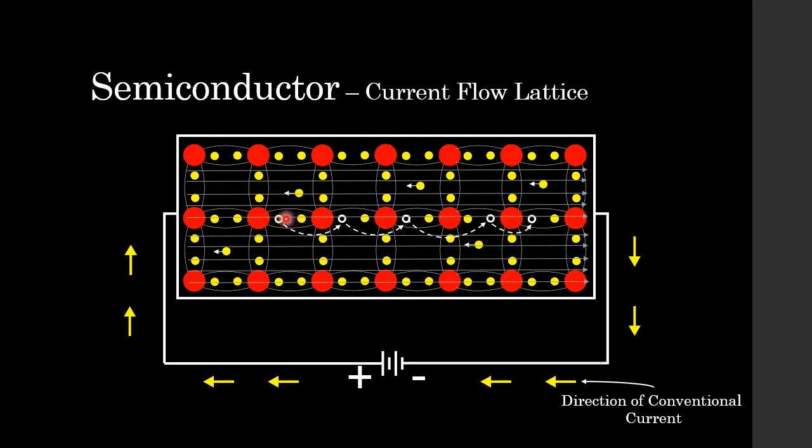Look at that, they are all moving within the valence band. So hole flow takes place within the valence band, whereas free electron flow, which is in the opposite direction to this electric field, is taking place, students, in the conduction band. So important to note that hole flow takes place within the valence band and free electron flow takes place within the conduction band.